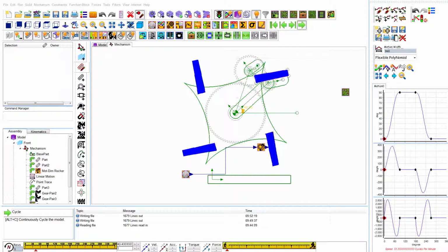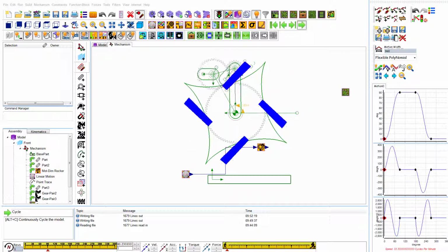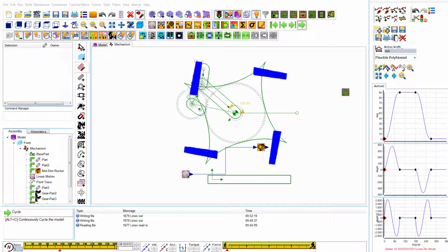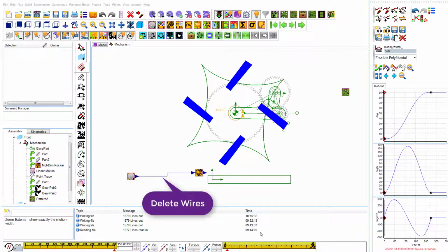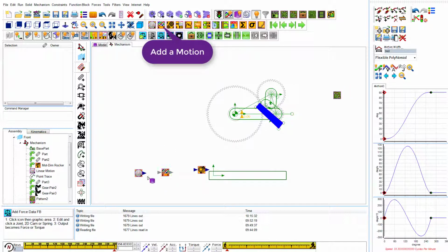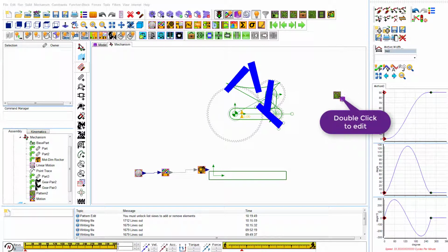So for example, if the machine angle is say 10 degrees, then 3 additional machine angles will be computed at 100, 190 and 280 degrees. If we want the crank driving the gears to index, then adding a motion to achieve this has an undesirable effect. The non-linearity of the indexing motion causes the additional phases to be drawn in different positions. You may or may not want this effect.